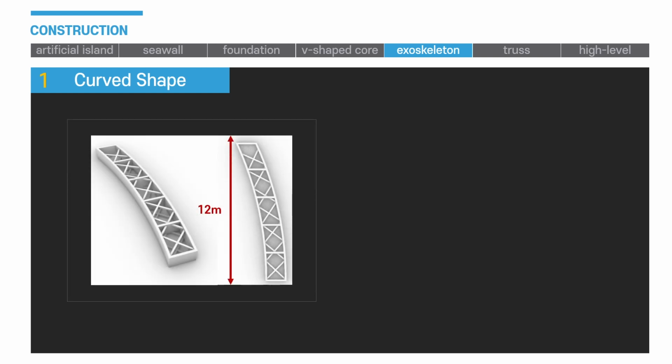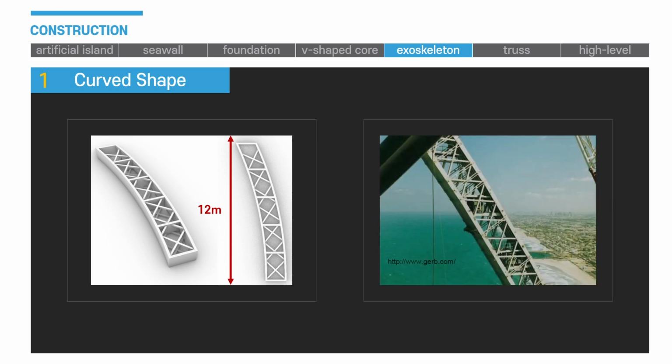To make the steel structure into a perfect curved shape, it was divided into 12 meter segments. The divided steel structures were able to effectively express curved shapes. However, the segments were still heavy, so the work was difficult. Because it was very difficult to adjust the angle to express the curve in the air, two tower cranes were used to lift it up at the required angle and connect the structure at the same time.